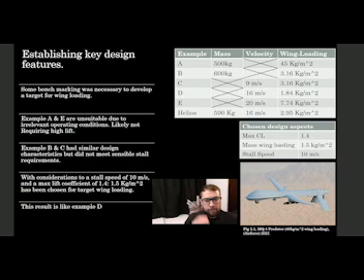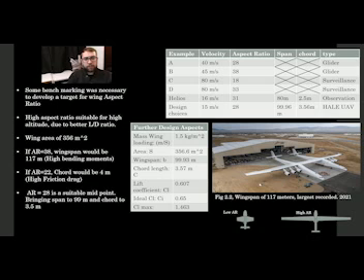Rearranging the stall formula finds that with a CL of 1.4 and a stall speed of 10 meters per second, a wing loading of 1.5 kilograms per meter squared would suffice, similar to example D. A higher aspect ratio is preferred on our UAVs because it will improve the lift to drag ratio. Lift performance is vital in high altitude, low density environments. Benchmarking a range of aircraft provided potential ARs from 22 to 38.